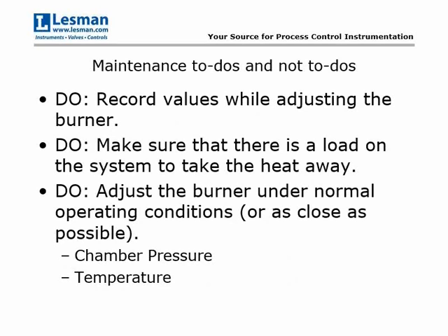This is not always feasible or possible, but things like chamber pressure and temperature inside the system will adjust our pressure measurements and our flows going into the burner. And if you set it up under one condition, or if you're doing some kind of recycle, and then you switch over to process mode and you've got a vastly different chamber pressure, then all of the values that you had previously measured are going to be radically different, and I'll show you an example of this later on in our presentation.